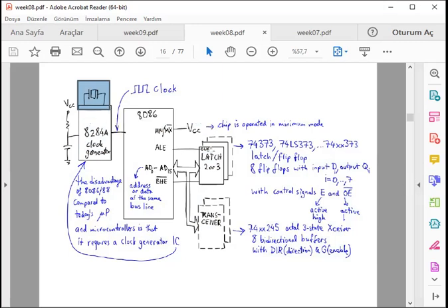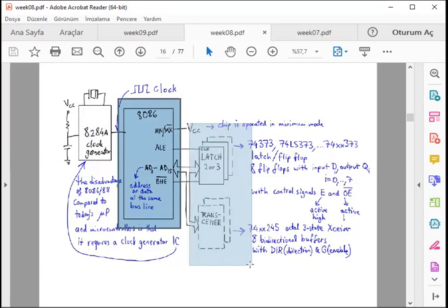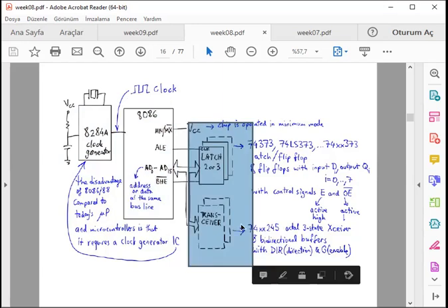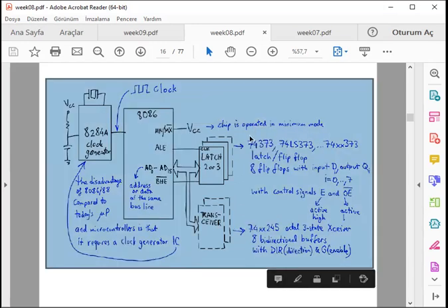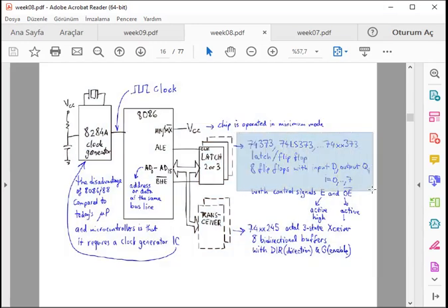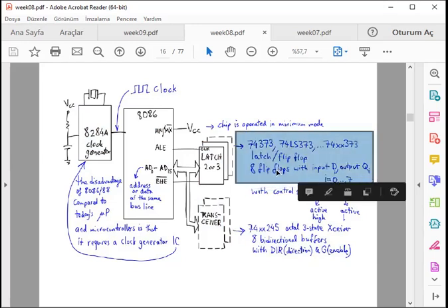And our microprocessor chip is connected to two groups of latches or D flip-flops. Each one has a byte length. For address pins, depending on 16 bits or 8 bits multiplexed forms, we need at least 2, maybe 3 latches to store the information in 20-bit format.